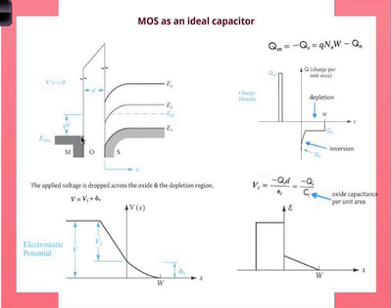So we know in this situation, when a positive voltage is applied, the inversion happens. And we know the inversion can be represented in the energy diagram by the bands bending such that the intrinsic level goes below the Fermi level, right? So it becomes N-type right at that interface. It's P-type far away. So that's inversion. Okay? So you have depletion happening in between, and you have an inversion layer.